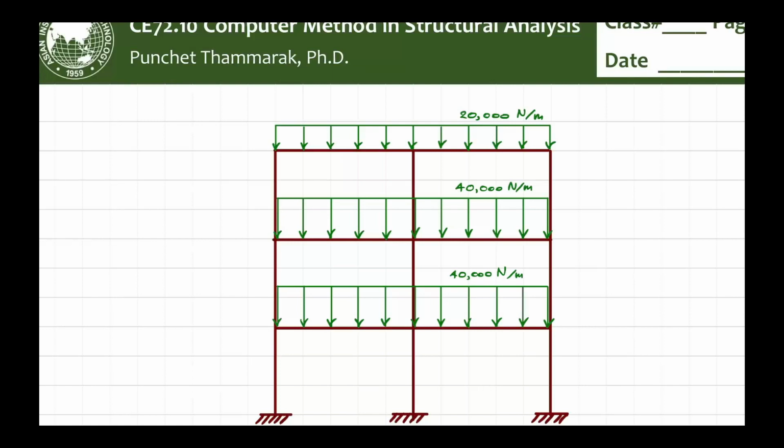There is some sort of coating called a pore blocker. That's a type that you can mix with some water solution. You spray on concrete, it seeps into the concrete, and then it forms crystals in the pores inside the concrete. You don't coat the top, you spray, let this solution seep into the concrete material, and then it dries out, it forms the crystal, and that crystal blocks the waterway. So this is the blocking from the inside, and then you can try to block from the outside, which is the coating. The coating can fail every 5 years, but this blocking system is going to last longer, okay?